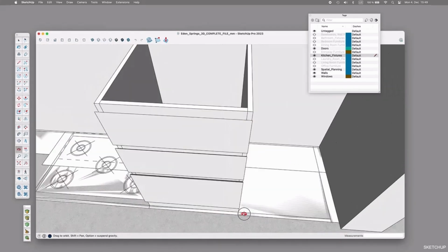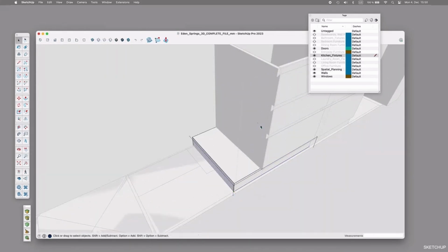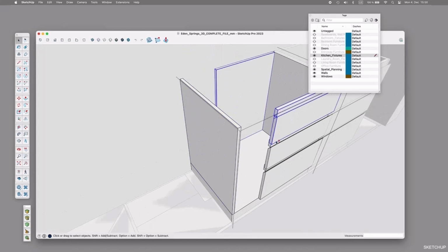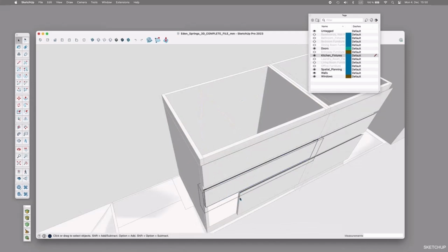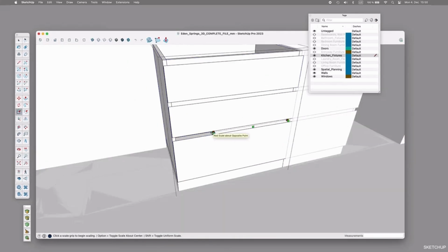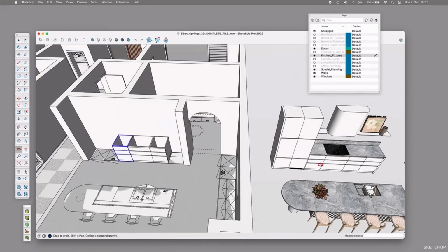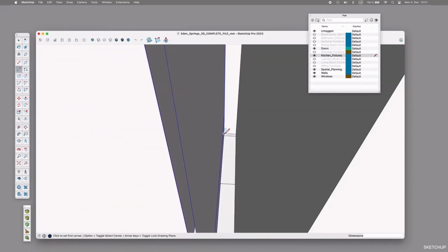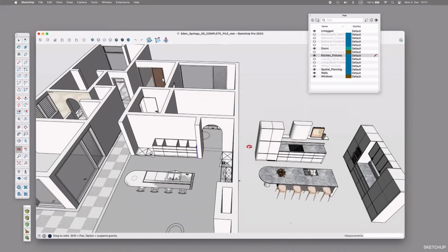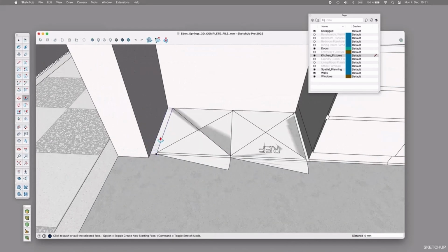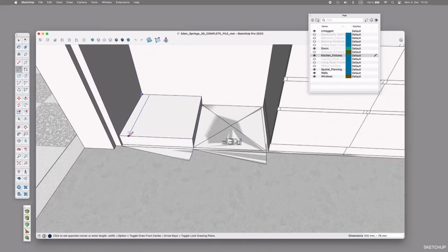You can then just copy the same model and adjust its size. I would not suggest using the scale tool on the whole cabinet box, but rather just push-pull single surfaces out, as otherwise you will also change the scale of the material thickness. If you start creating elevation drawings later on, based on this 3D design, your measurements have to be exact. If you want to recheck any measurements, you can always refer to my PDF plans or open the kitchen cabinetry file, which was included in this module package.